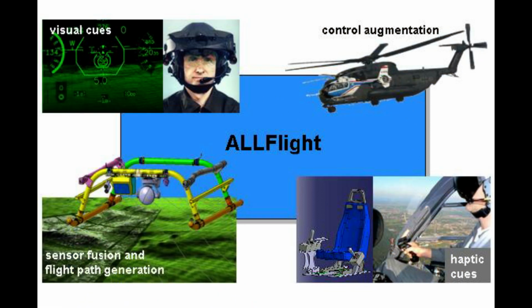Active augmentation systems. So-called active augmentation systems use electric actuators that provide input to the hydraulic servos. These servos receive control commands from a computer that senses external environmental inputs, such as wind and turbulence. SAS complexity varies by manufacturer but can be as sophisticated as providing 3-axis stability. That is, computer-based inputs adjust attitude, power, and aircraft trim for a more stabilized flight.